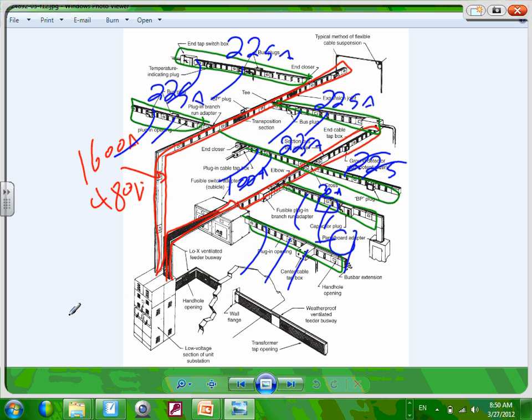When I'm done, I roll the machine, connected to the energizer, to the next location, weld there, and continue along the track. That would be a great application for a trolley busway. With trolley busways, the connection moves. Unlike plug-in busways, where the connection is permanent and you have to physically, mechanically unplug it and plug it somewhere else if you were to move.